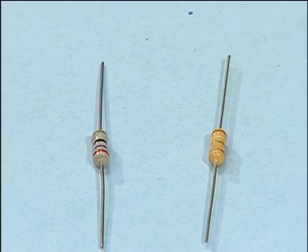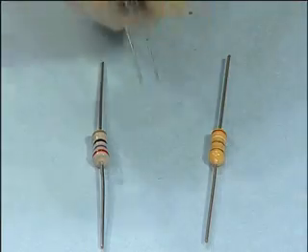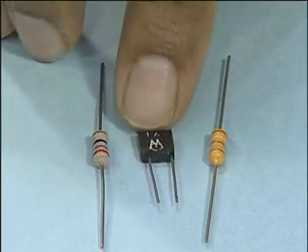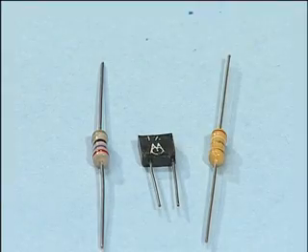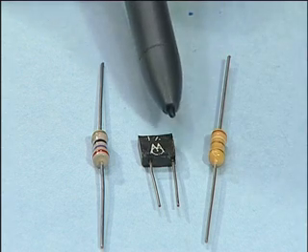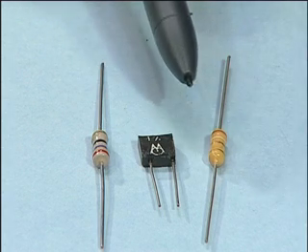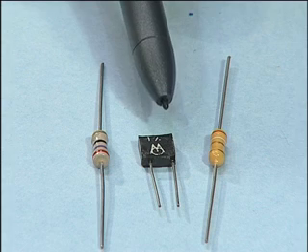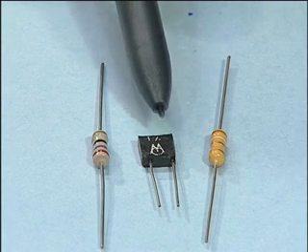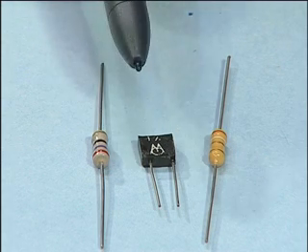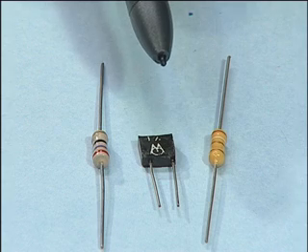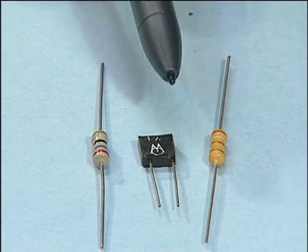I will put in a different type of resistor. You see this resistor here. This is a box type, made differently. This is called a metal film resistor. This is more precise than the carbon resistor in terms of variation with respect to temperature and such, and they are generally used for frequency tuning components.